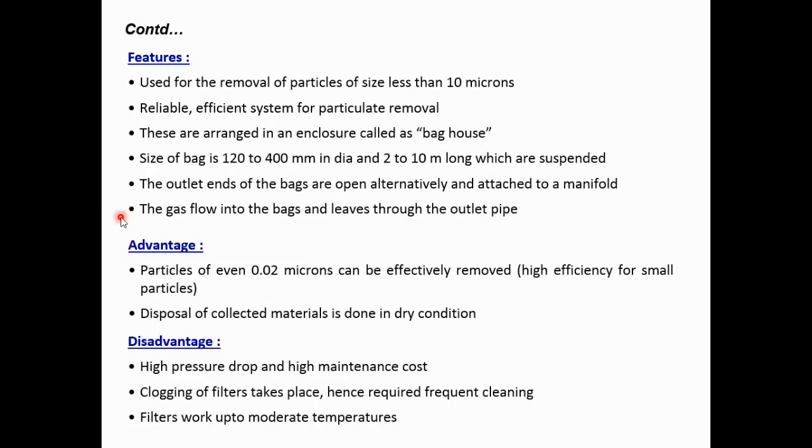You can dispose the dust which is collected in the hopper of the bag filter, or use it in a recycle or different way. If you are using a wet separator, meaning you are sprinkling water, then the dust particles may stick to the wall, corrosion may take place, and various other issues may be there. But here there is no such type of issue, and the maintenance cost and other cleaning costs are very efficient in case of bag filter.